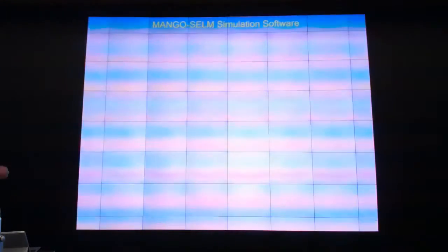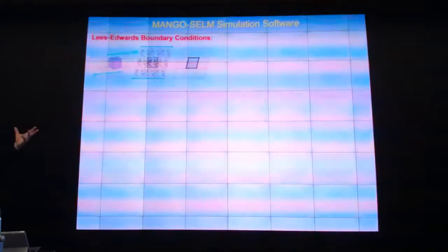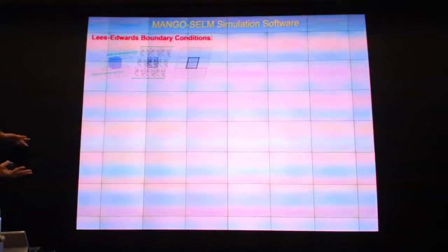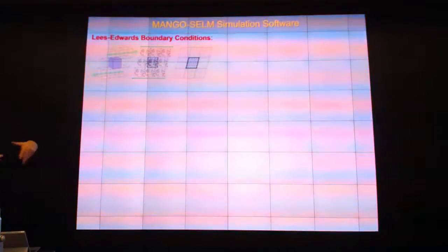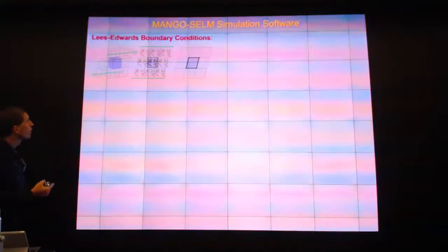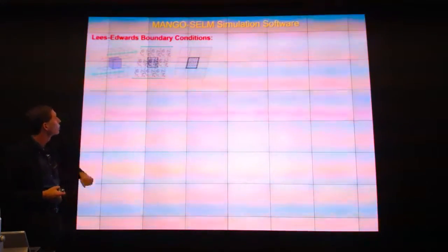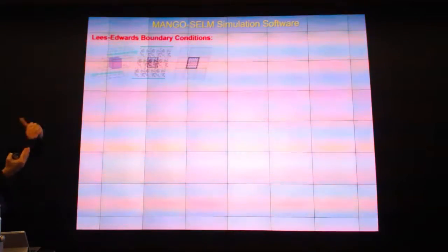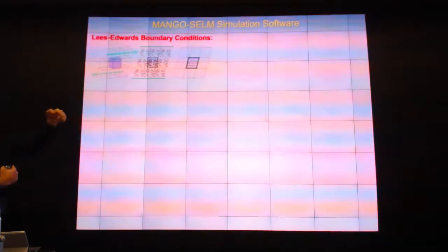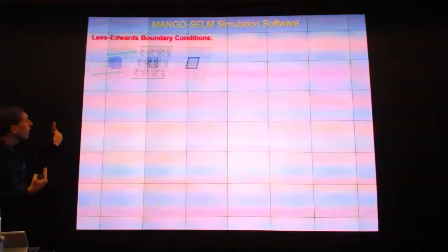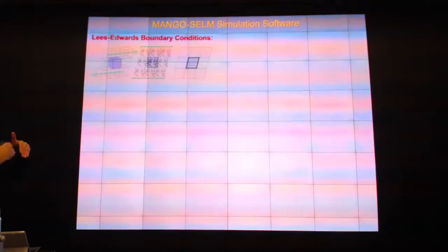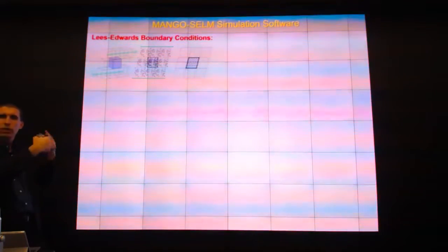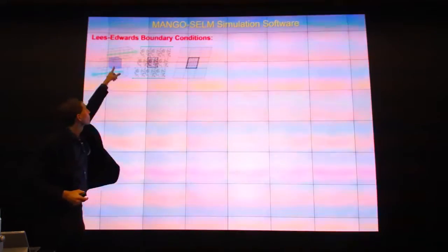And so in molecular dynamics, this has been modeled by what's known as the Lees-Edwards boundary condition. So rather than doing an affine transformation of your entire lattice or network, which would impose the corresponding response, you can look at this as a sliding bricks model. So you have this centralized brick. The periodic images, instead of being in the normal location, are shifted slightly. And these can run in the opposite direction on the top and the bottom. And effectively, because you see a shifted periodic image, it's as if the material is being sheared, at least near the boundaries locally. And then internal interactions within the domain set up the response.